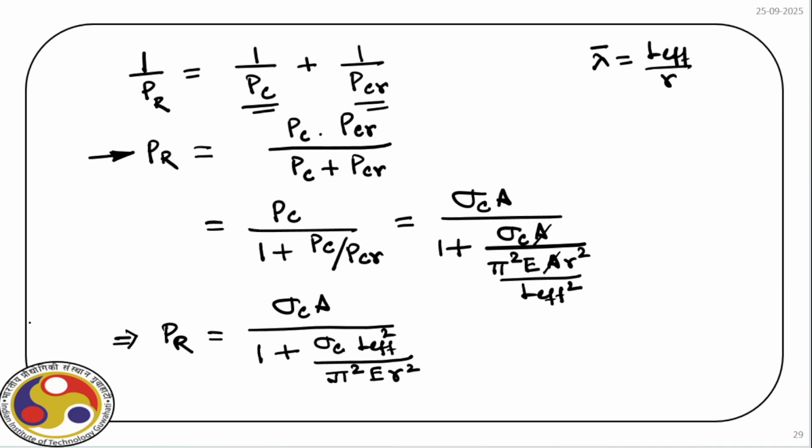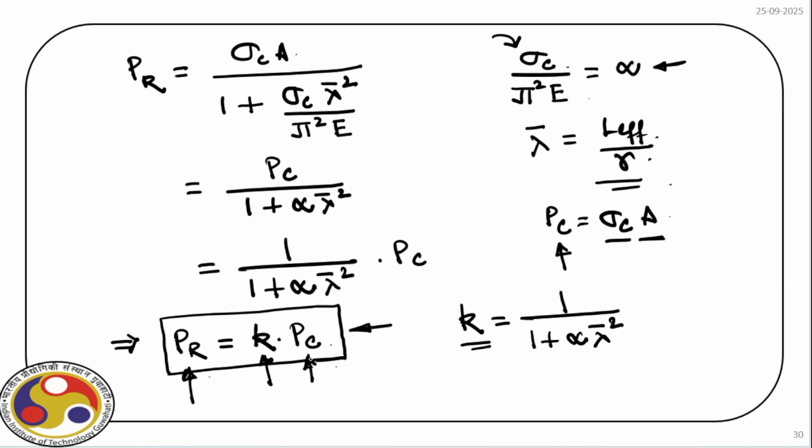And the advantage is, normally in the design codes this expression is given, and where we find out PC and multiply that with a factor, you can see here, and then we can get the effect of buckling, and we get the combined effect which is embedded in the Rankine's empirical expression.